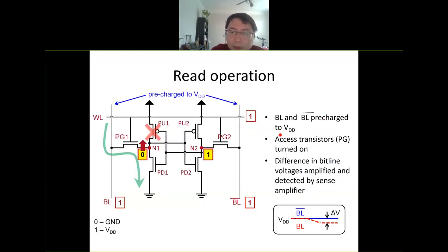Okay. So we need to treat the bitline bar as a capacitor. We have this wire capacitance for the bitline. Why is that? The bitline is a metal wire. It's an interconnect. And we learned in lecture 2, you have multiple bit lines, you have multiple wires. Between wires, you have isolation.